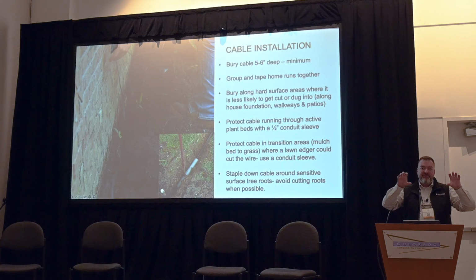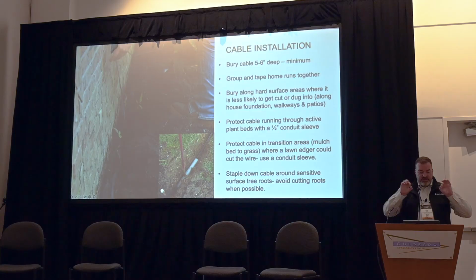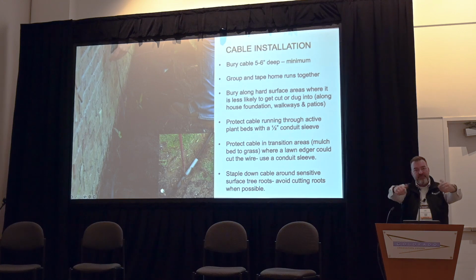So if you're doing architectural lighting, up against a foundation is a great place to run them, because nobody's going to be digging flowers there. You can take all your home runs and bundle them up. You can zip tie them. I use electrical tape or whatever. Put them up against that foundation, bury them, and they'll be out of the way pretty well.